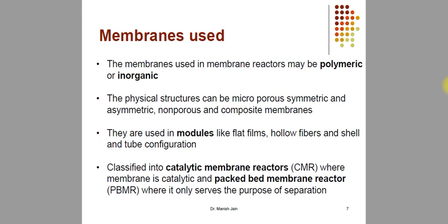You can reduce the energy consumption, because you can reduce the capital cost. Why? Because when you use the membrane reactor, you need only a single chamber for reaction as well as separation. So you need not transport the fluid from the reactor to the separator. Then you have to again give energy for separation, then remove the energy from the separator. Those steps can be excluded from this membrane based process.